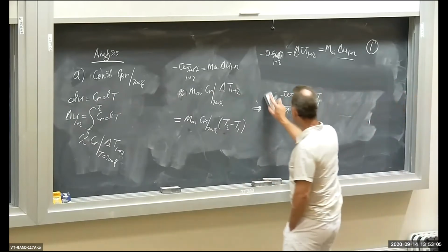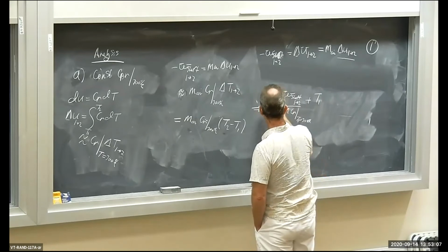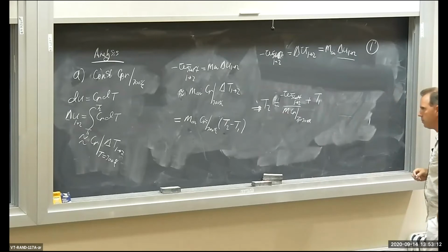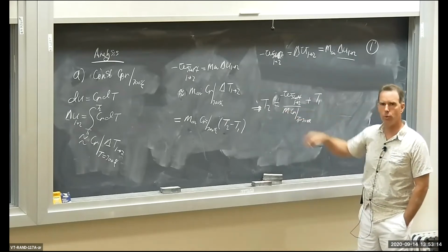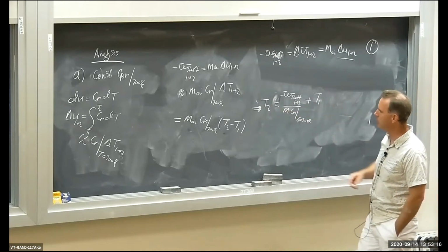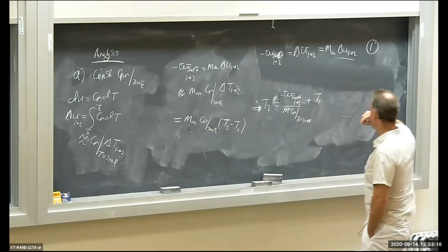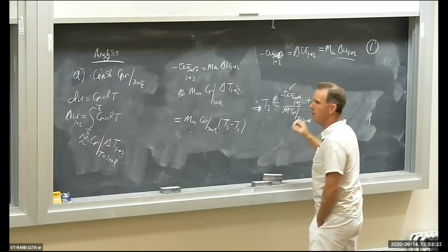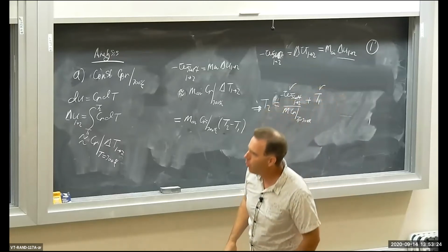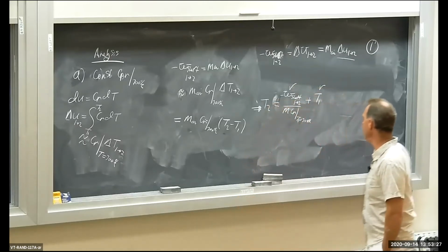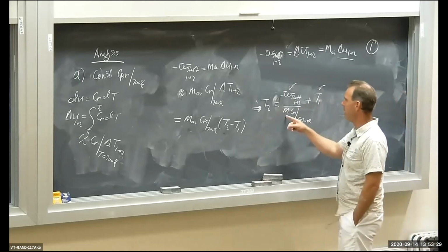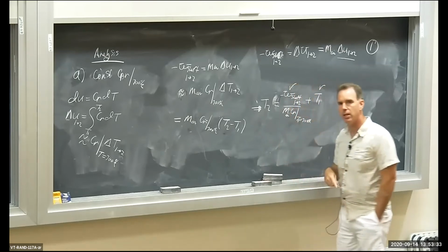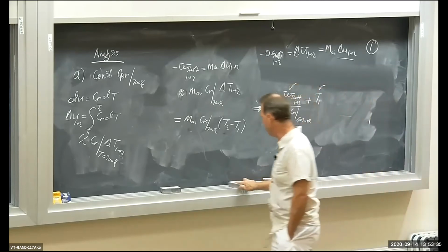Now, let me get this looking a little bit better here. That looks better, okay. If you want to put an approximately equal here, that's fine too, okay? Because we're assuming constant specific heat. Let's see here, I have W shaft. I have T1. T1 is 293 degrees Kelvin. I don't have the mass of the air, and I don't have the specific heat. Let's see if we can find out what these are.